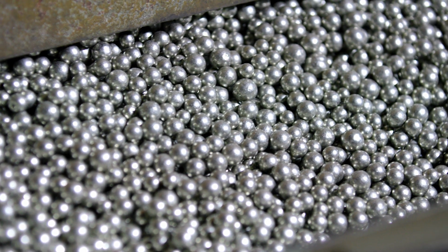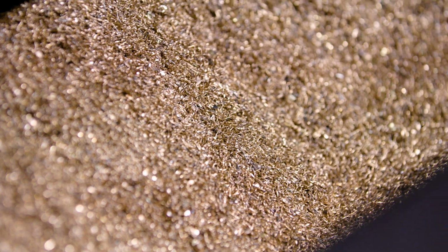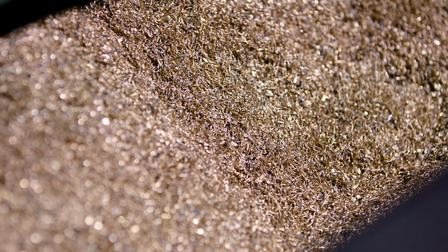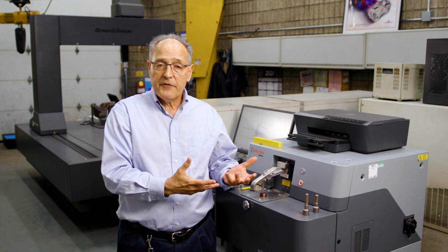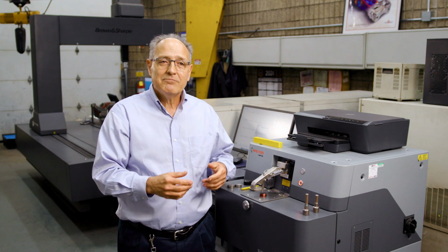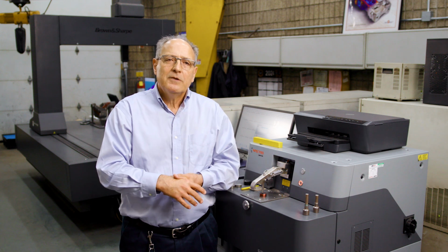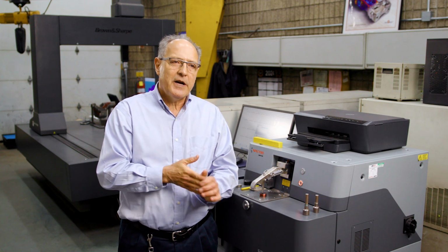There are other elements that are important. For example, copper. Even though copper is a soft element, it makes the iron stronger. We run different grades. Some are softer, some are harder, stronger, and the element that we add is copper. Not much, like 0.8% would make the strongest ductile iron that we make.